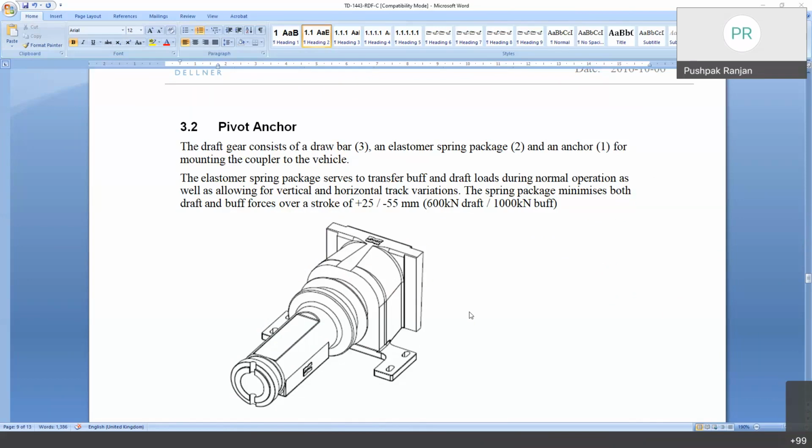What about the talkback system, sir? Emergency talkback is there. In addition, inside the coach there are two emergency push buttons. If any person presses the push button in case of emergency, it is a latch type of switch. It will get engaged and give a continuous alarm to both guard and driver. Basically, the guard or driver has to apply the brake. That is the arrangement here. Okay, sir, thank you. Whatever we have in MEMU or EMU.